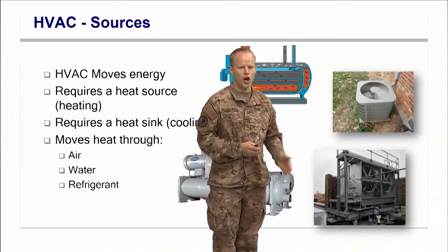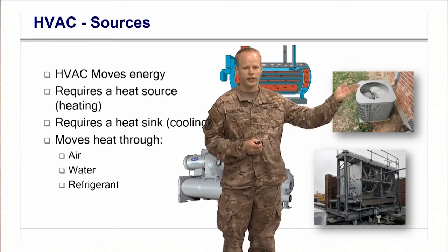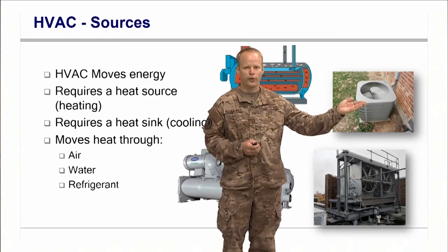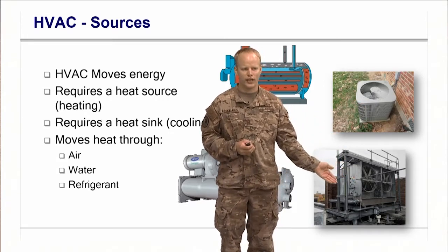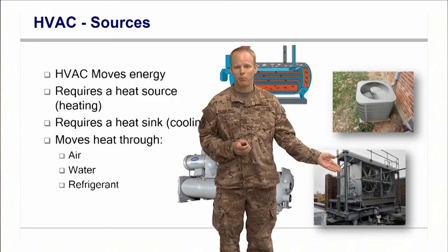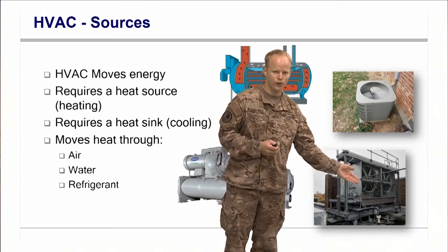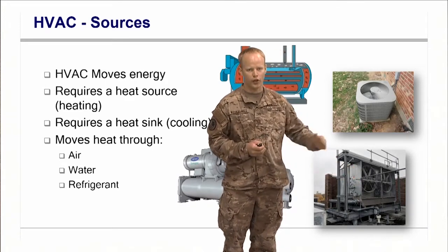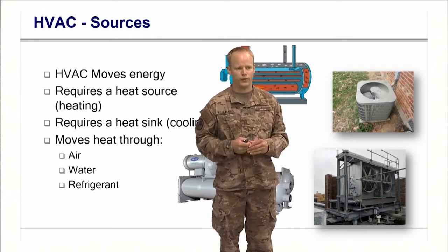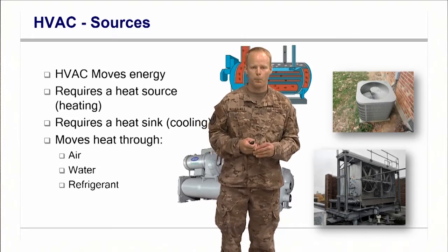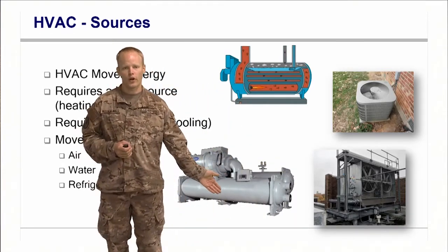So in all of these systems for cooling, we have to move the heat outside. Your condensing unit, you're going to move it outside through refrigerant and reject it to the air. Your cooling tower, you're going to reject to the air through evaporation by pouring water over coils and running air across it. As you can see, there's fans over here that blow air through the water, cause evaporation, and decrease the temperature of the water. And the middle step with our cooling tower is our water-cooled chiller.